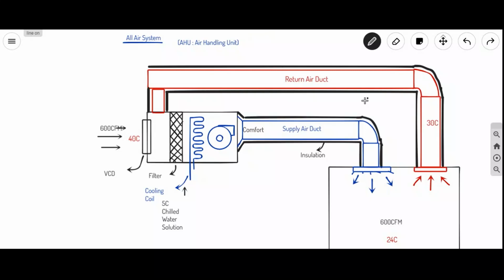You have asked a good question. The insulation materials are styrofoam, sometimes glass wool, and nitrile rubber. In some applications, for example in hospitals, we can't go with glass wool or fiberglass insulation. So particularly in hospital applications, we choose nitrile rubber.